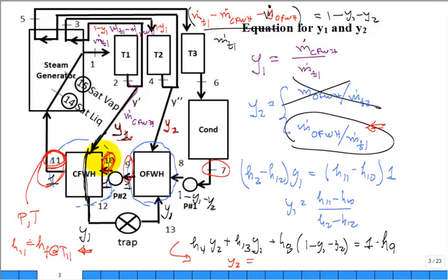So it's actually better to know it's isentropic. That's my assumption. It's isentropic flow through the pump, and so the minimum work is VDP. So I've just kind of given you a hint. You can pretty much avoid using the compressed liquid tables. It's a lot faster without needing to do a double interpolation.